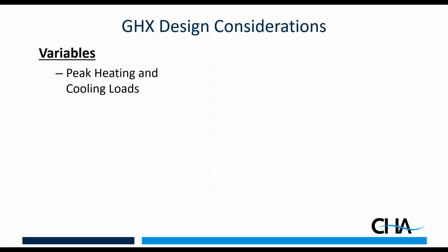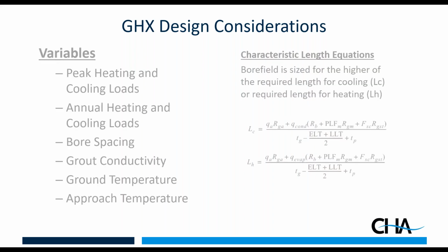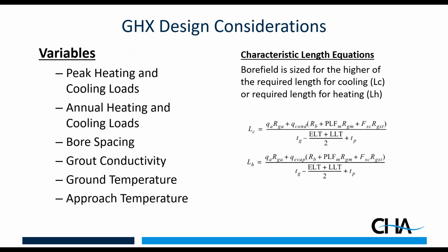The thing that makes designing ground heat exchangers unique is that with most HVAC equipment, the thing that we care about is peak heating and cooling loads. That's how we size our equipment. And especially with variable speed drives and variable speed fans, we have a lot of latitude in how they operate in between those extremes. But with ground heat exchangers, we are very concerned not only about those peak heating and cooling loads, but what the annual heating and cooling loads are.